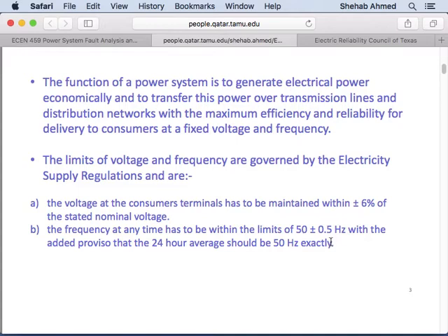The rotating magnetic field, the time-varying magnetic field. So if you put a piece of wire in a time-varying magnetic field, then voltage will develop. If voltage develops and you close the loop with a load, then current will flow. If current flows, then you have force. And that force will be opposing that prime mover force that was put in.